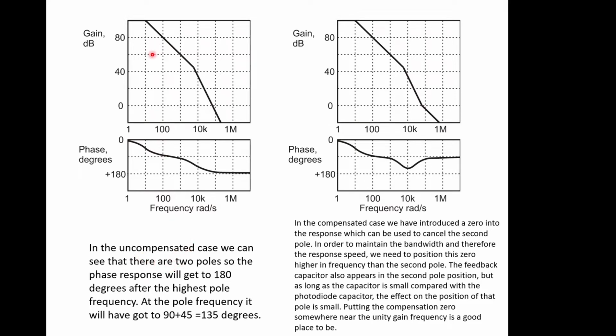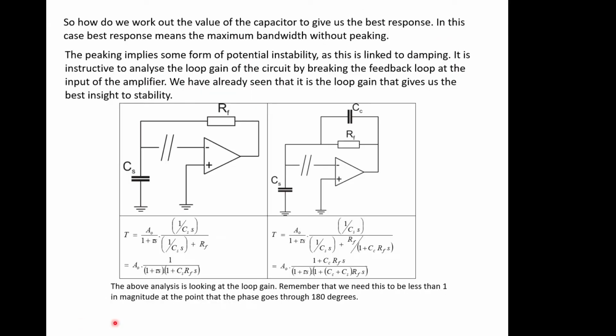Right, okay, so we hadn't got to this bit, so that's where I was, so that's all right so far. In fact, what we'll do is we'll just go back, because I was probably covering up this bit of the screen. Okay, so we were just looking at the formulation of this equation and how it looks, and we spotted that this had a single pole response similar to this one, where the coefficient of capacitance, if you like, was both the capacitances added together, where in this case it's just 1.